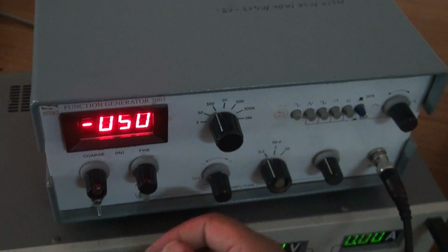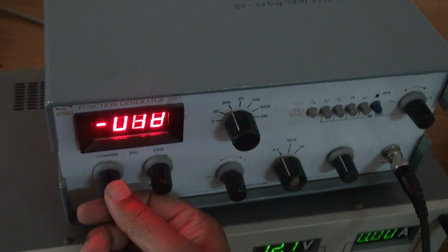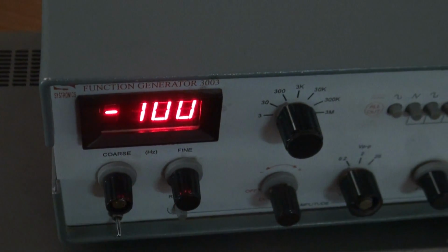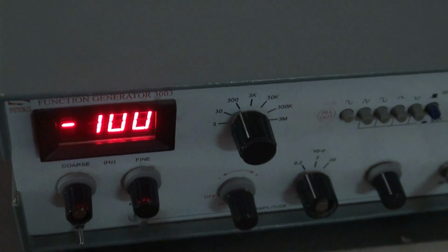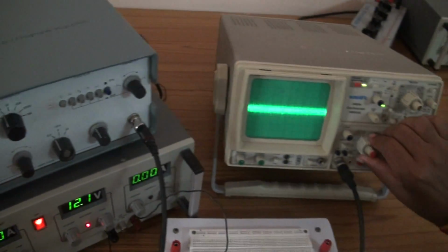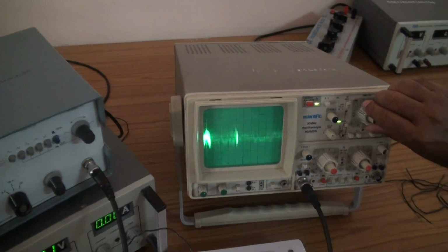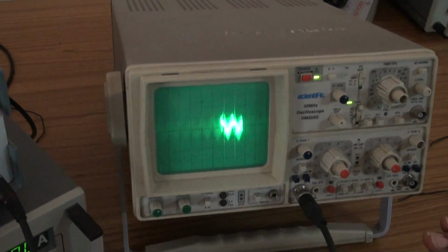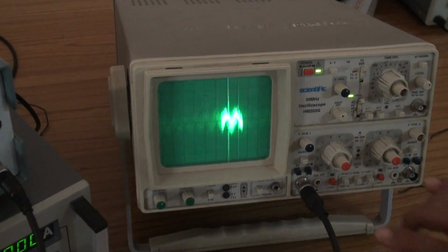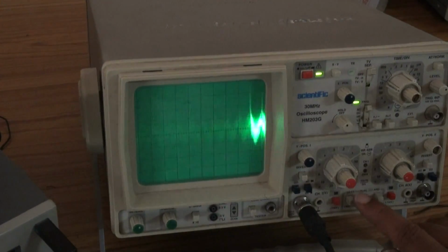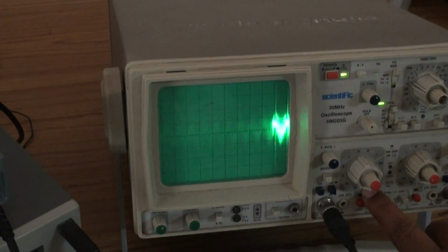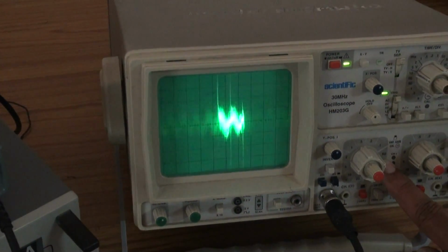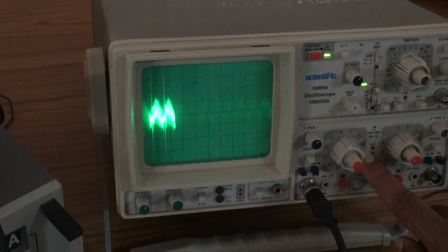So now by varying this, we can set to 100 Hertz. This is 100 Hertz frequency. Let it be 1 or 2 Hertz more or less, it doesn't matter. And check how much is the output voltage. This is the actual output voltage. At low frequencies, this amplifier gives very small output. That is the reason approximately you can take this as 10 millivolts. Okay, at 100 Hertz input, the output is 50 millivolts.